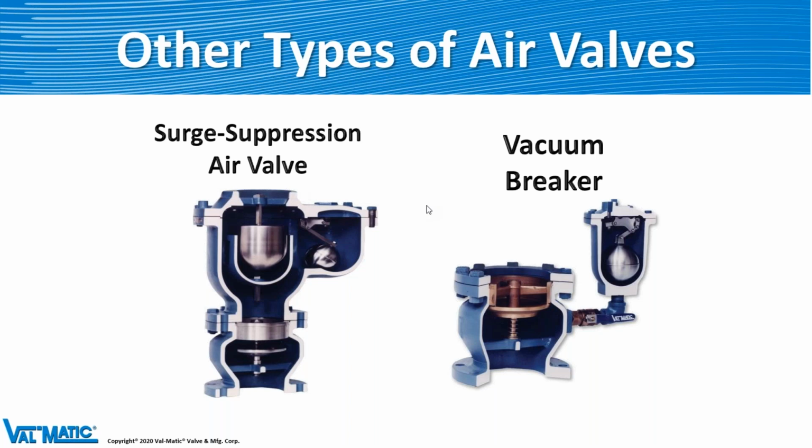So it's a special setup, and we need to know all your combinations of what's going on and all your design information. And then a vacuum breaker: if you always know you're going to have a problem with your pipeline creating a vacuum that impairs everything, then this might be the good valve to put in there in that application.